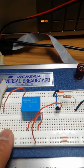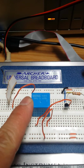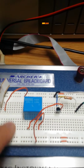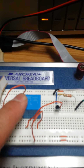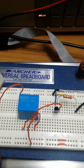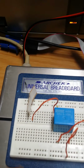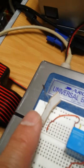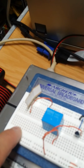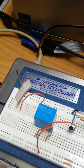Anyway, what the transistor does once it's activated is energize the coil inside the relay, and once this is energized, it essentially switches over the relay inputs so that the igniter here, which is a standard small engine igniter, I don't know if you can see it clearly, is triggered by closing the connection in the relay.